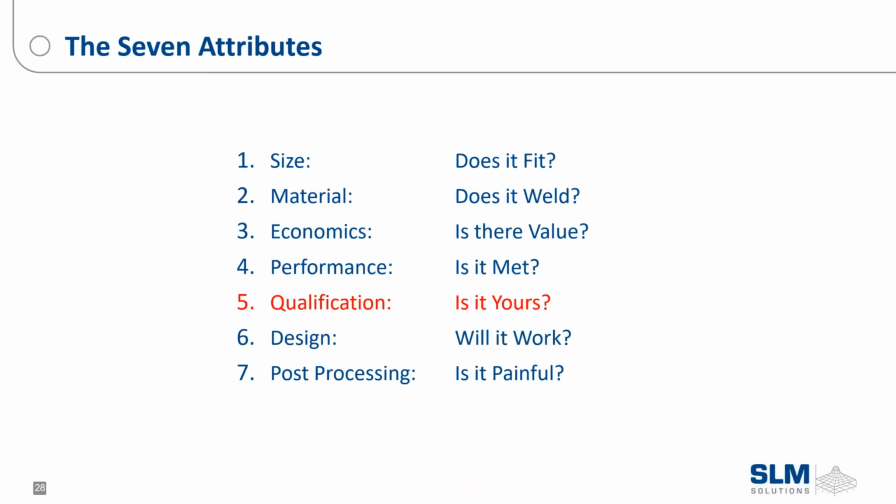Accuracy. This is accuracy across the machine as far as part accuracy. We can hold anywhere between 50 to 100 microns based on calibration and the tolerances set up for the part you're trying to produce. So we are not going to get a direct one-to-one, perfectly sized part every single time. There's about a 50 micron tolerance there, and that has to do with the next thing, stress. The powder bed is preheated to up to 200 degrees C, but since it's a welding process with miles upon miles of weld bead being laid down, there's a lot of stress buildup during the production of these parts.